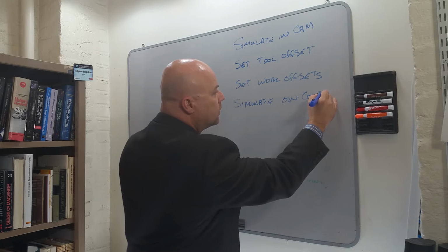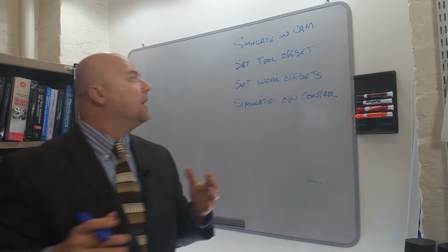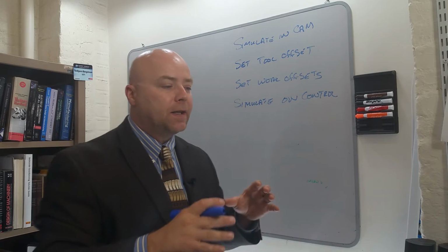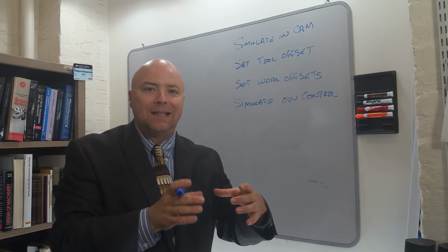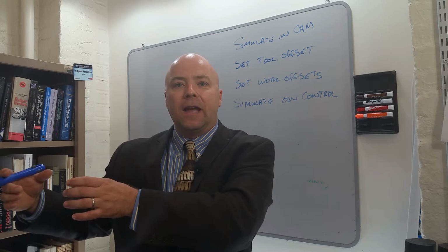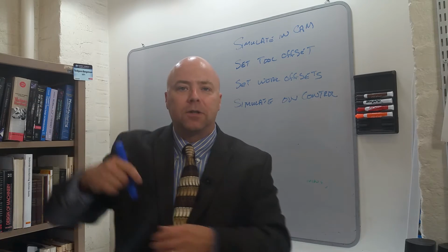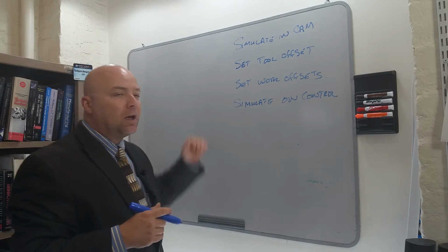On the controller. So I want you to simulate on the controller, and that tells you a few different things. One, it tells you if you physically put the workpiece in a spot that the machine tool can reach. So it might be possible to put the workpiece near the edge of the machine tool's travel and then have it be so that the tool can't reach all the positions that you've commanded it to go to. That'll tell you if you've done that.